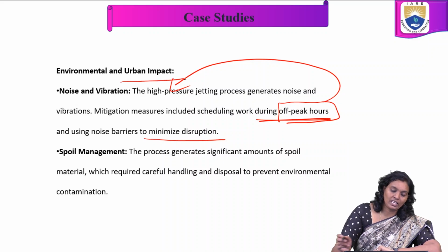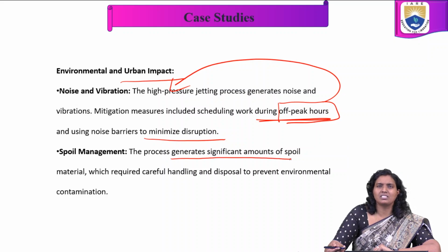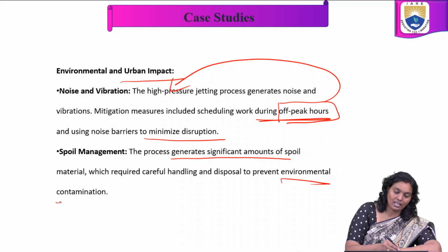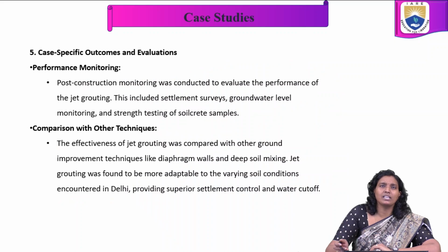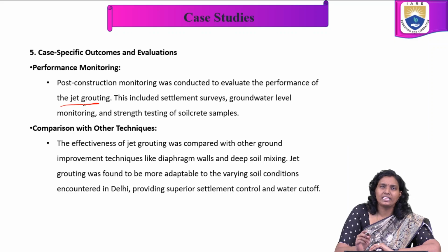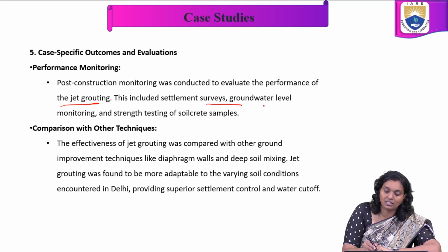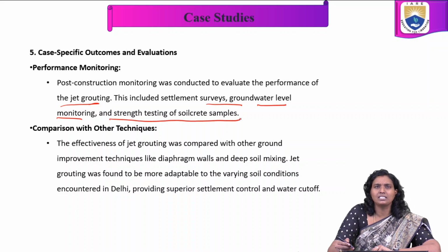In this spoil management, the process generates a significant amount of spoil material, which requires careful handling and disposal to prevent environmental contamination. Next come case-specific outcomes and evaluations: performance monitoring and comparison with other techniques. Post-construction monitoring was conducted to evaluate the performance of jet grouting. This includes settlement surveys, groundwater level monitoring, and strength testing of soilcrete samples.